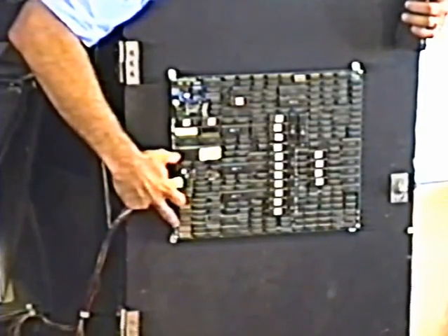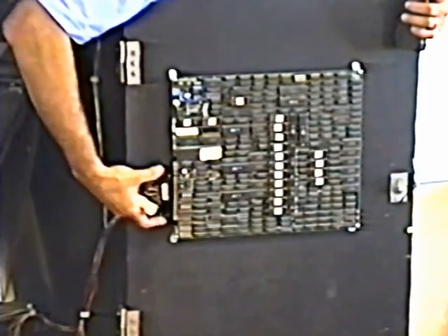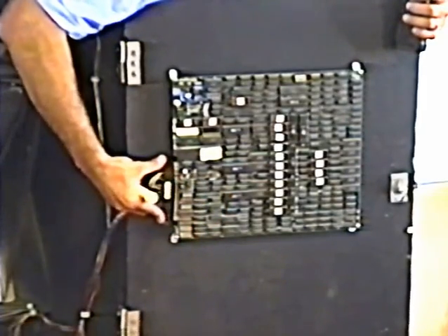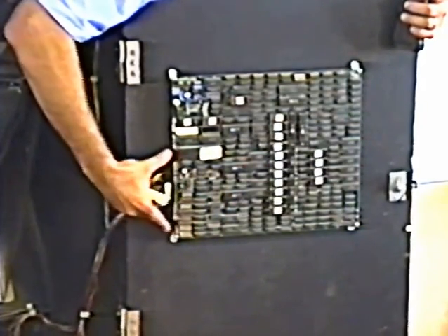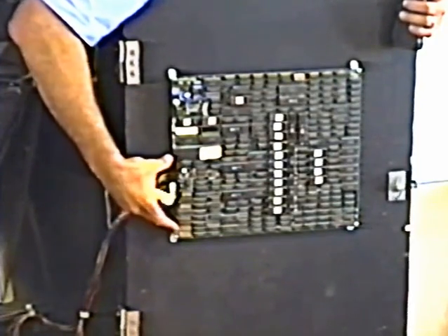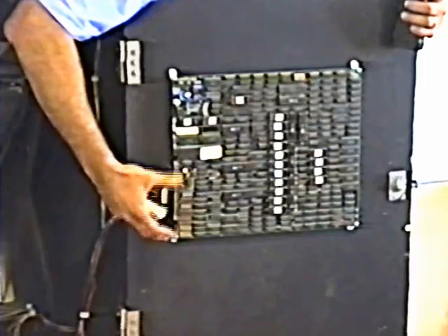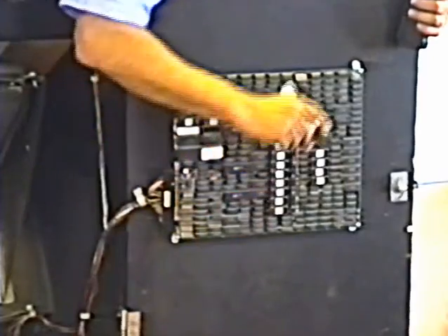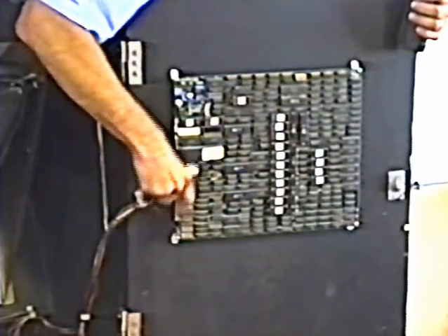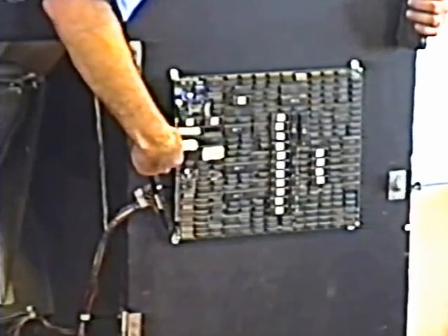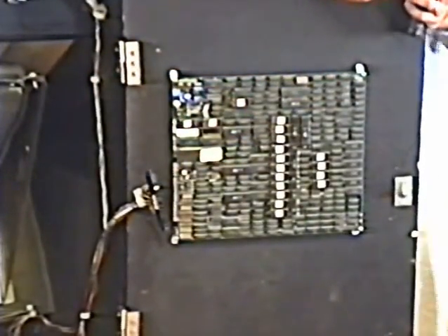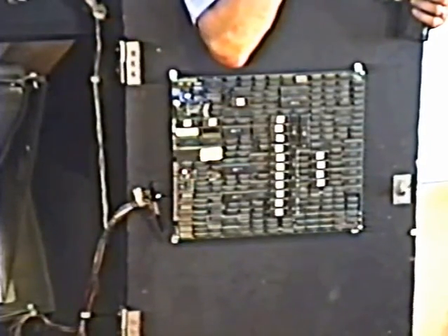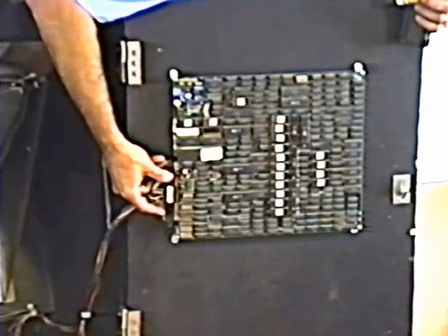So before you adjust the power supply, I do this all the time. At the very least, with the power turned off, because you never plug in anything or unplug it with the power on, other than the AC power cord, obviously, you might try plugging and unplugging this a couple of times. That's something you should always do anyway, because just the process of plugging and unplugging it cleans it off and makes a better connection. But it's best to clean this connector off, this card edge off, with a pencil eraser or even a dollar bill. Just take a folded up dollar bill and rub it against the connector, and it cleans it right off. That's pretty important, because you don't want to have any dirt at all on the connector.